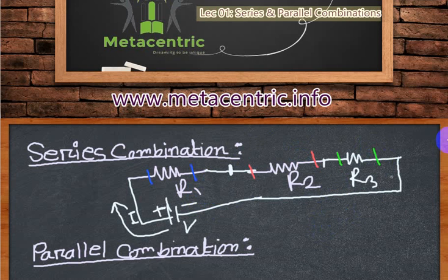Okay, to calculate voltages, suppose this is another, different circuit. Suppose this resistor is Ri, and there is a voltage source V. To calculate the potential difference between the two terminals of Ri, one terminal is this and another terminal is this. So we should put a multimeter or voltmeter to calculate the potential difference between its two terminals. So let the voltmeter be placed like that. Then we will have the potential difference, or voltage drop, across Ri in that manner.